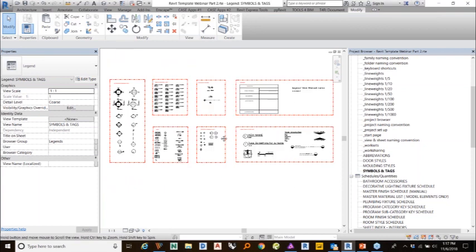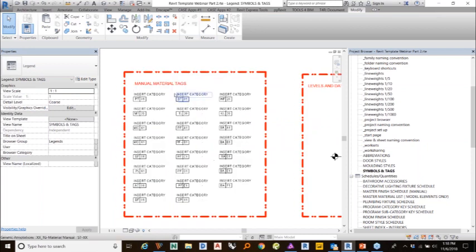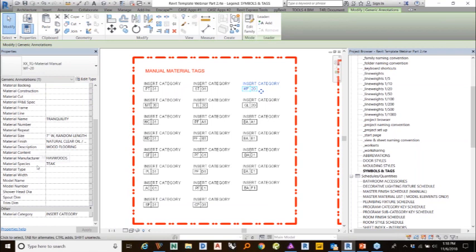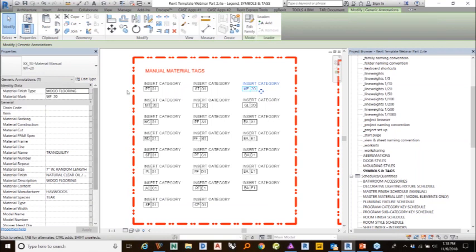And now I'm going to move very quickly into how to set up pre-baked schedules that work off of existing tags. I want to quickly look at something I had to build for this template, which I call a smart dummy tag. This tag is essentially a series of instance parameters built into a tag, which you can see here under General, and they include everything that's material based as well as finishes for bath accessories and plumbing.